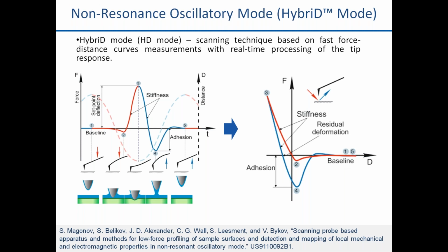And having the force curve and applying certain mathematics, we can calculate the quantitative mechanical properties, adhesive properties, and of course, first of all, we are getting the topography of the sample, keeping constant the maximum force minus the baseline.